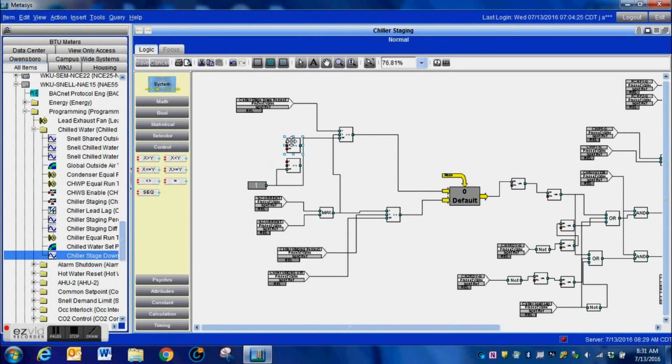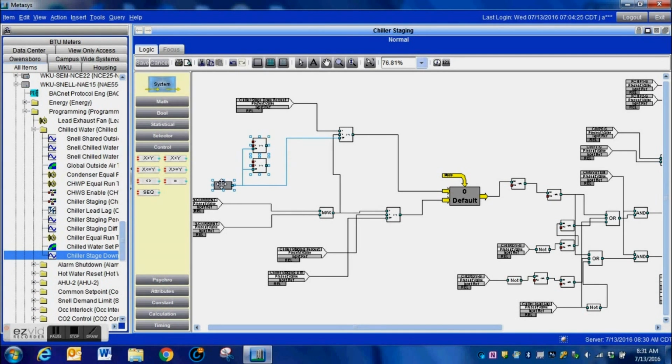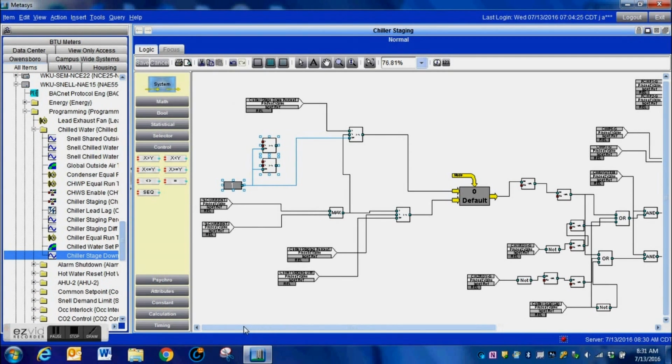So now I'm going to pull over a second comparator block. Now I also am going to need an additional floating value. Let's pull these back here to give us a little more room to work with. Sometimes we can get quite complex in the way that these work. I have connected this one floating value. You can see I have it connected to the differentials on all three of these comparator blocks, which works fine, no issues whatsoever, does exactly what I need it to do.